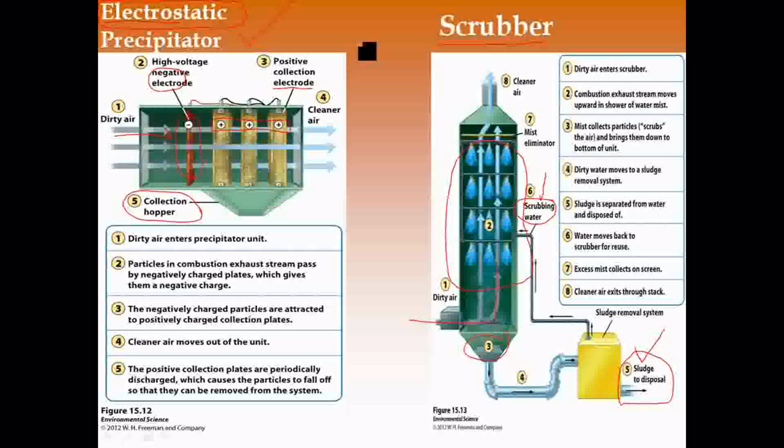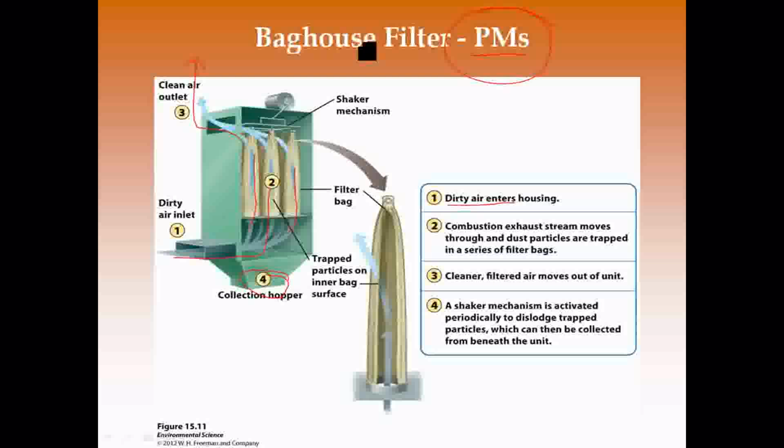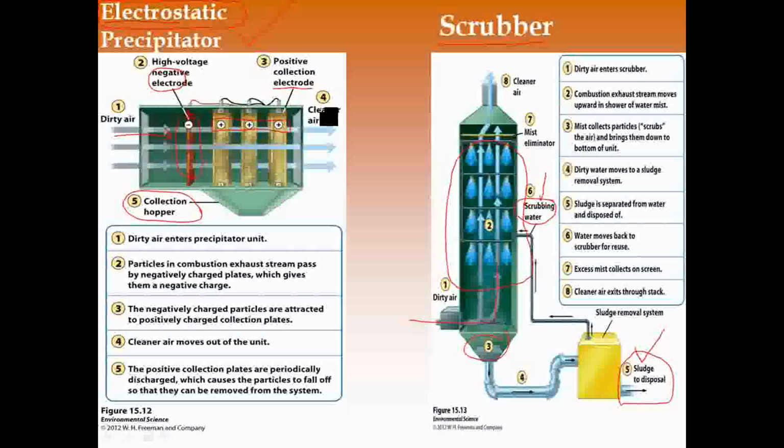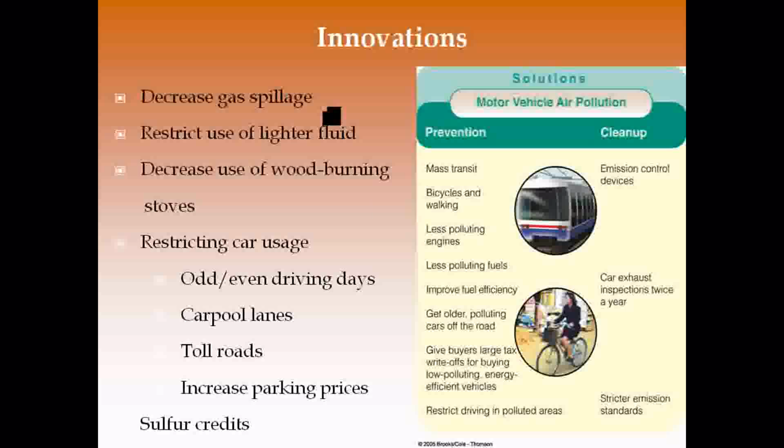And even going back to the baghouse filter, this pumping process is the least of the energy users, but this shaker mechanism runs on electricity. You can see the motor up here. So no matter what we talk about with these cleansing activities, they use energy. And if they use energy, that means we're having to pump that much more up through the smokestack at the power plant. Having said that, these techniques are very important for cleansing PMs. They also cleanse an awful lot of sulfur.